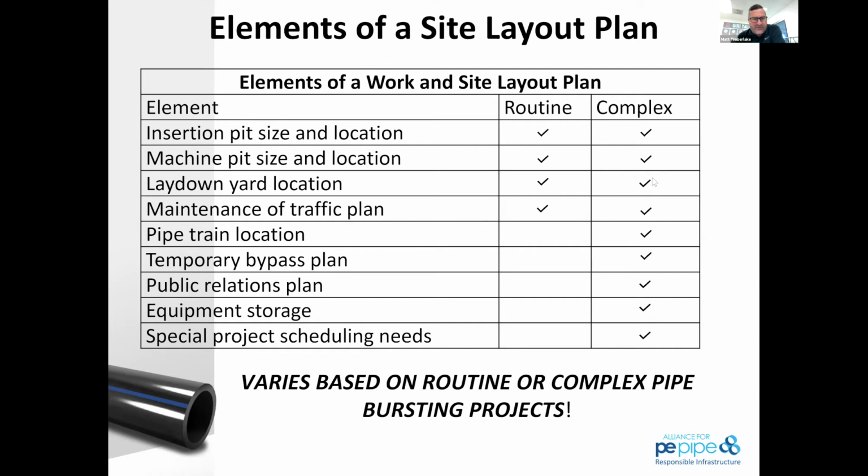And then the maintenance of traffic plan. So, are we going to do lane shifts, or are we going to actually have to close lanes? And then as part of that traffic plan, we also want to include how people are going to access their driveways, how business locations are going to access.